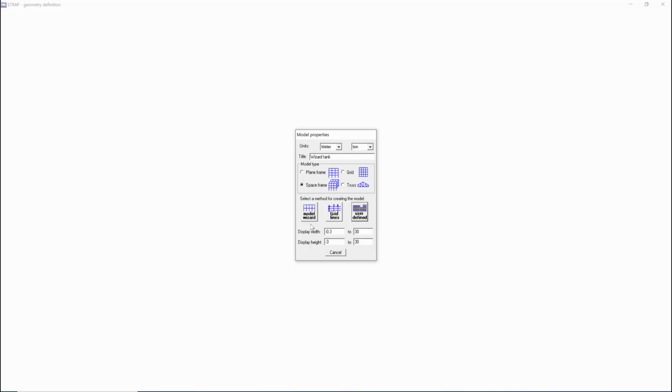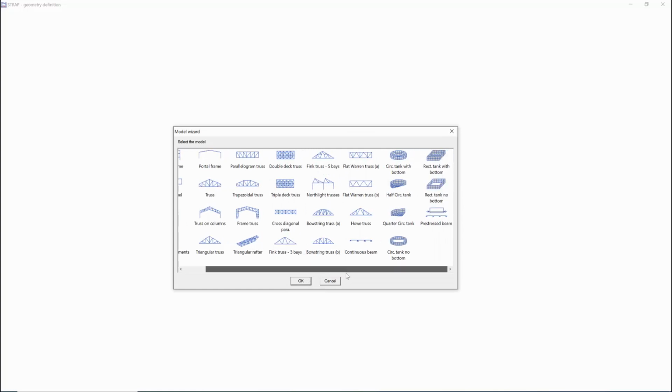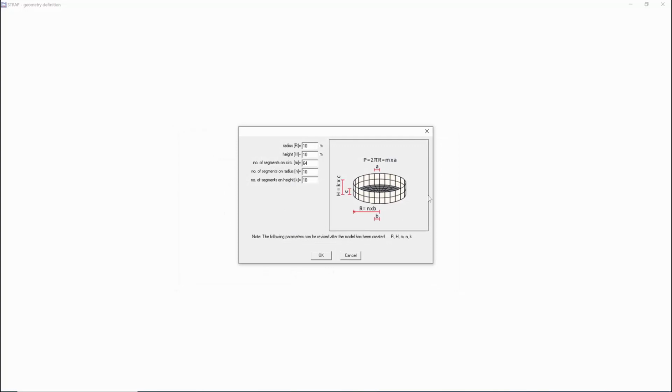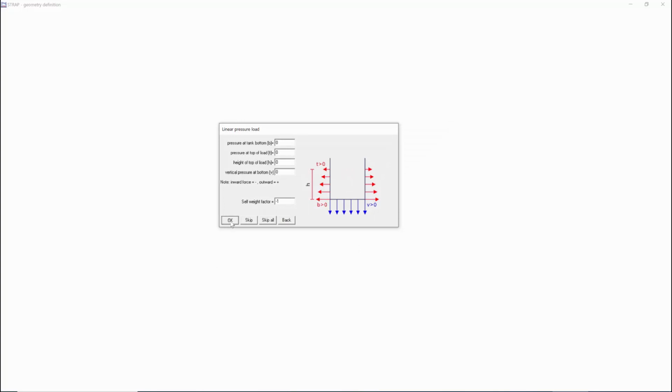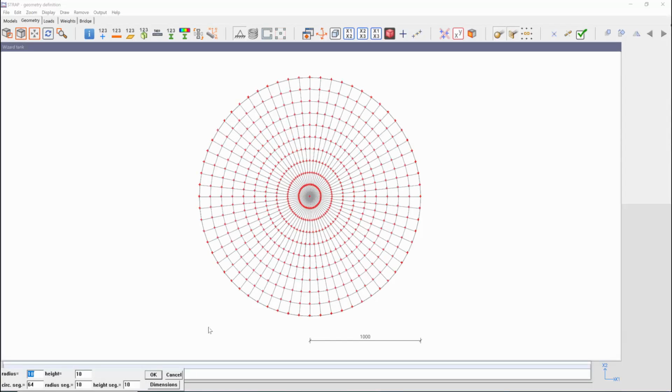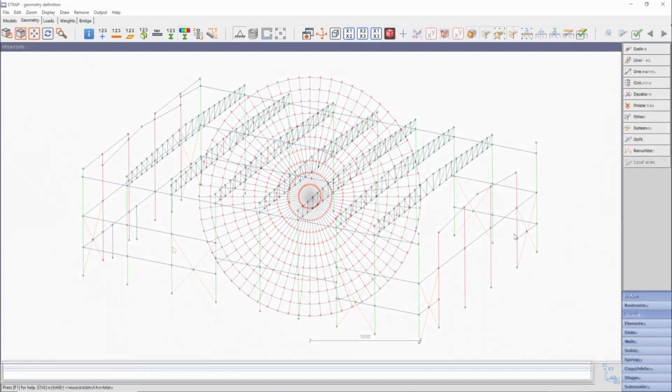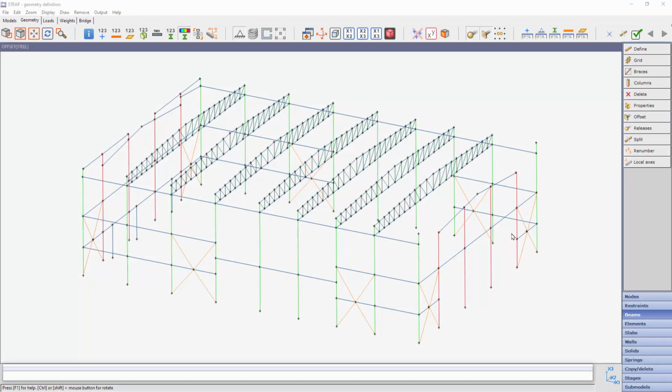When selecting Model Wizard as a method of creating a model, the whole process is improved, and additional drawings are added. For beam offsets, we added several commands, and the definition menu is revised. These commands are designed for revising an analytical STRAP model that was created with an IFC file via AutoSTRAP.